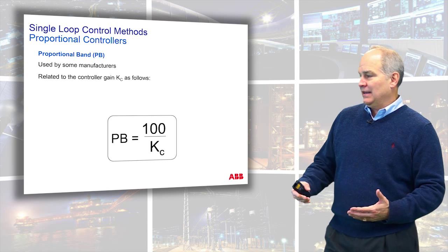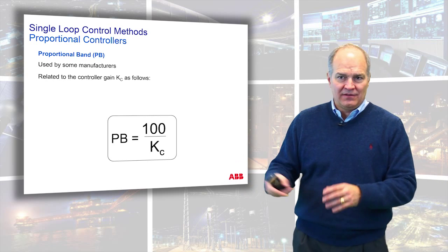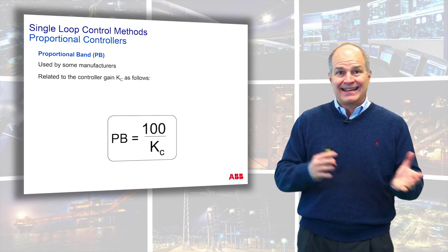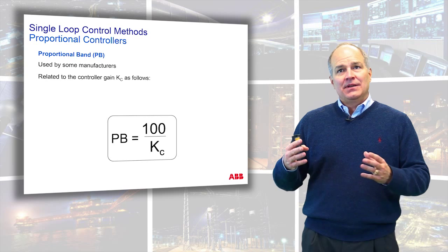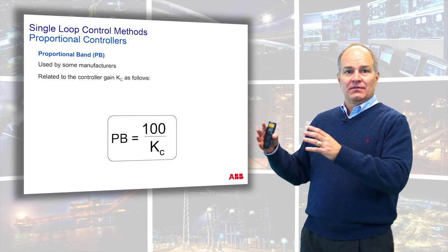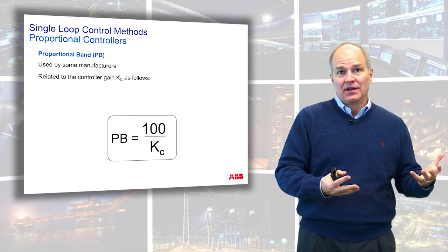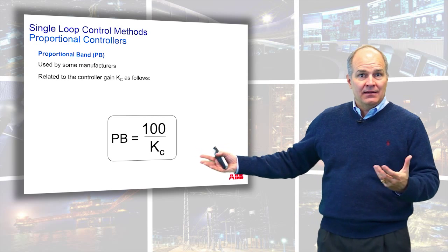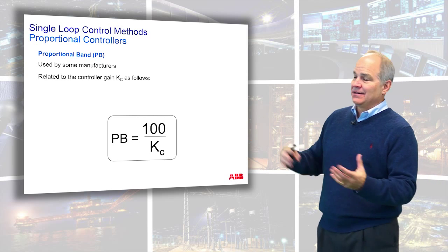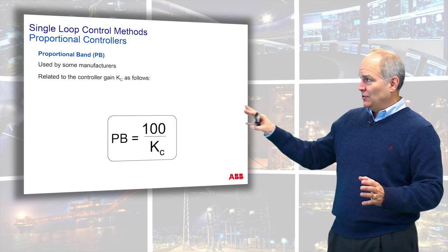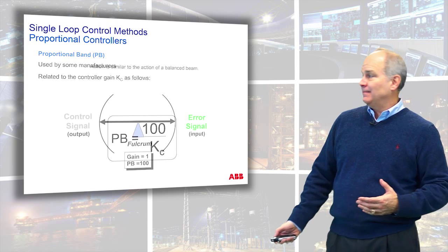I would talk to an E&I staff, so I need to put a control gain of 0.5. And he said, well, I never use anything other than 200. I mean, we were saying exactly the same thing, but he was working on a controller that operated in proportional band, and I was thinking in terms of a control gain that was a gain, not a proportional band. So it can be that simple that can throw things off. You have to understand the difference.